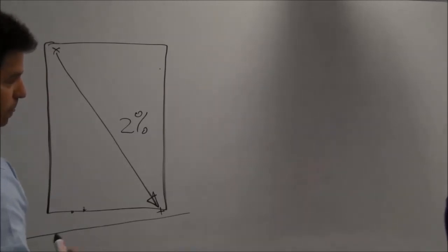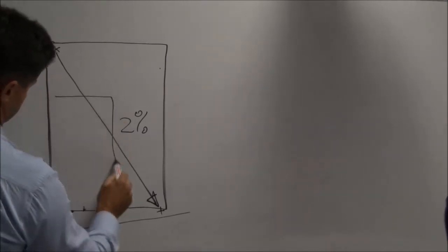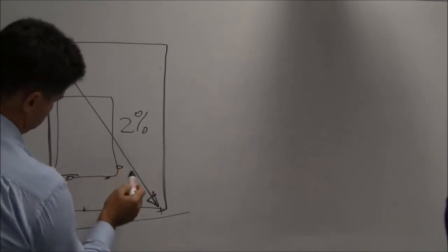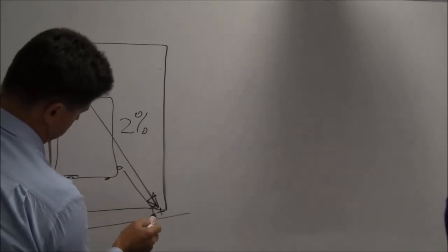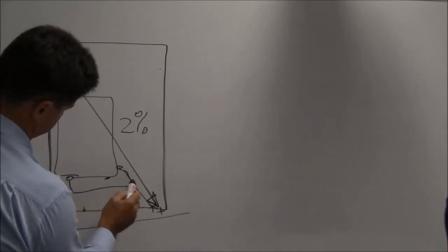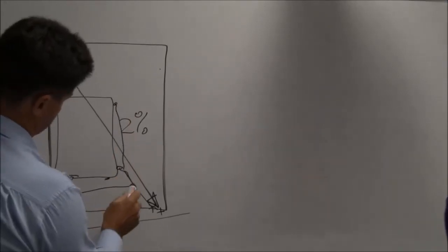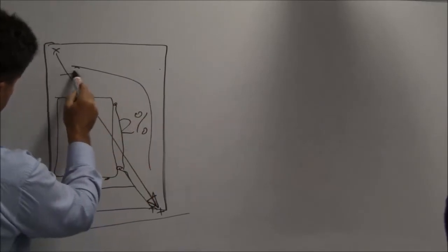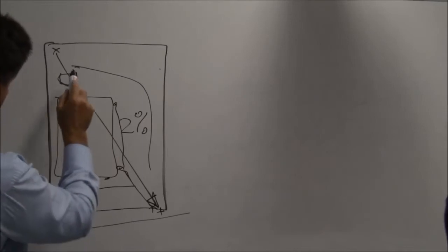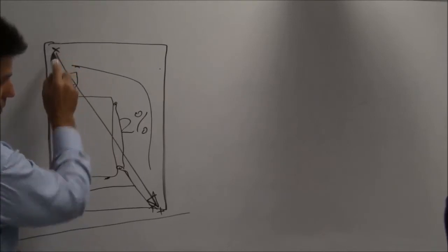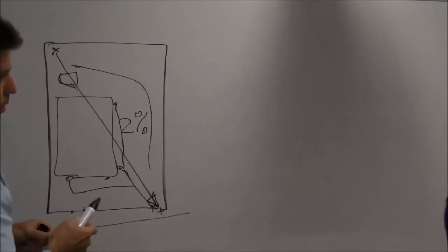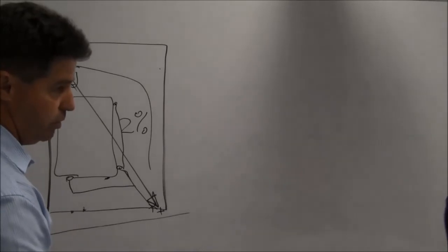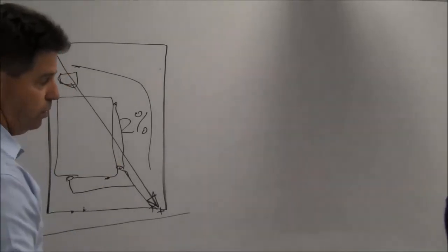So if we put a building over that, and we have downpipes that are associated with it, and we have a stormwater system that may end up at the same place, that's our discharge point. They all connect in as they come through the site. Whether it's overland flow or whether it's actually into a pit and then piped out, that's the time it takes from point A through to point B. It may be anywhere between 5 minutes up to 15 minutes generally, which is all we deal with for the smaller lots.